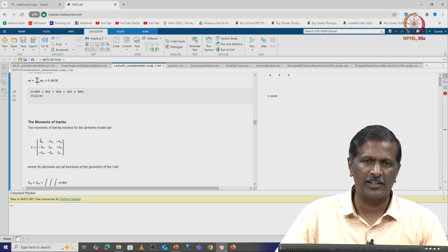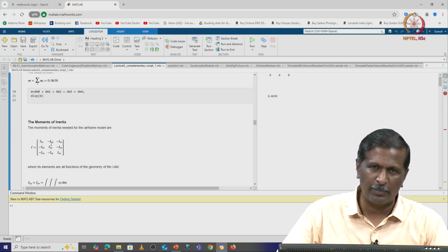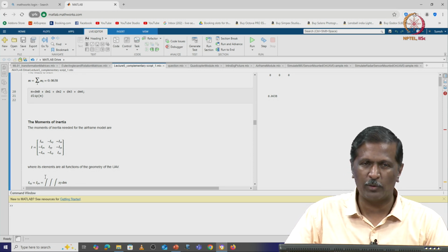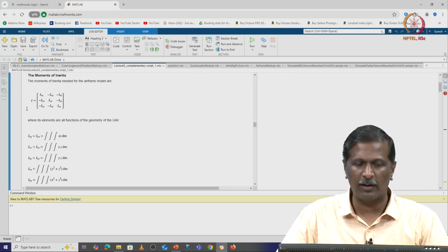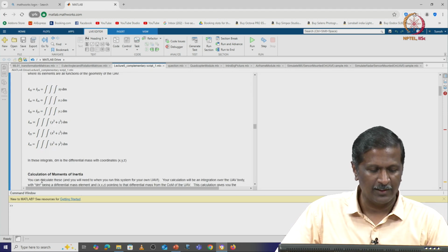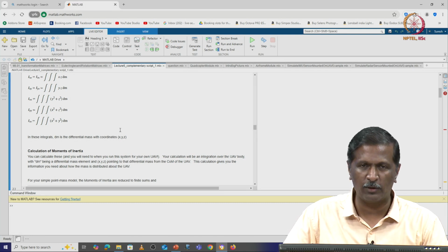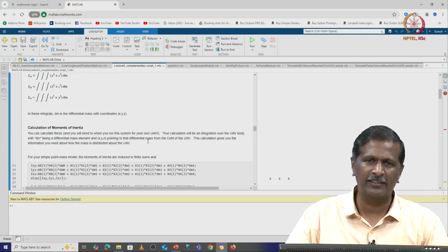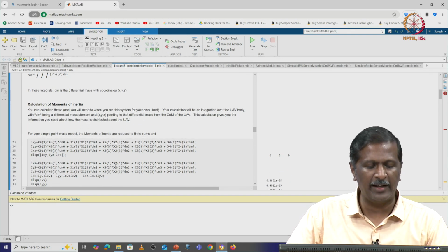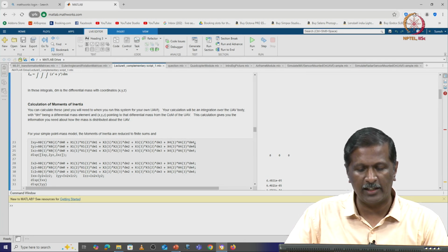For equation of motion derivation, we assume that it is symmetric, right. Otherwise, you will have x component, xy component, xz component, and similarly for yx, yz, zx, zy, and you will have diagonal elements Ixx, Iyy, Izz, right. We need to compute all of this, right. So, to compute all these, we need to define where your mass is and how the distribution is going to be, so that we can compute. Either you can do your CAD design and bring those values, or you need to define where is your x naught, where is your dm naught, dm1, dm2, dm3 and dm4.